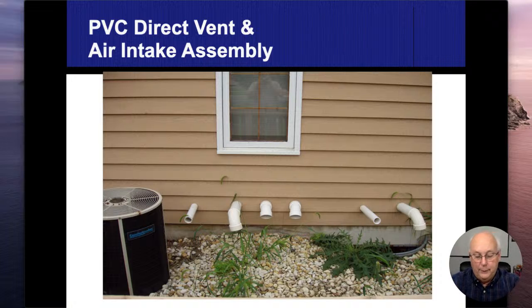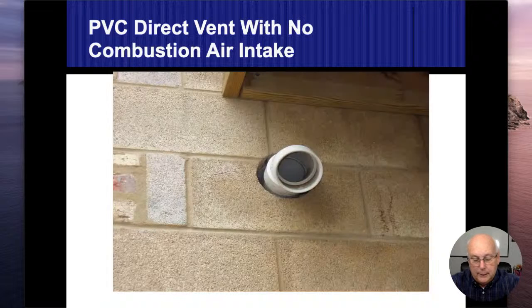And if this is a sump discharge here, I don't know if that has enough oompa to get past that window. And then if this is a water heater discharge here, I think I'm blowing that right into that window well, and that would cause it to come into the house. So anytime I see stuff that's messy like this, I get a little panicky and a little nervous, and I just start taking pictures and diagramming everything quite a bit better.